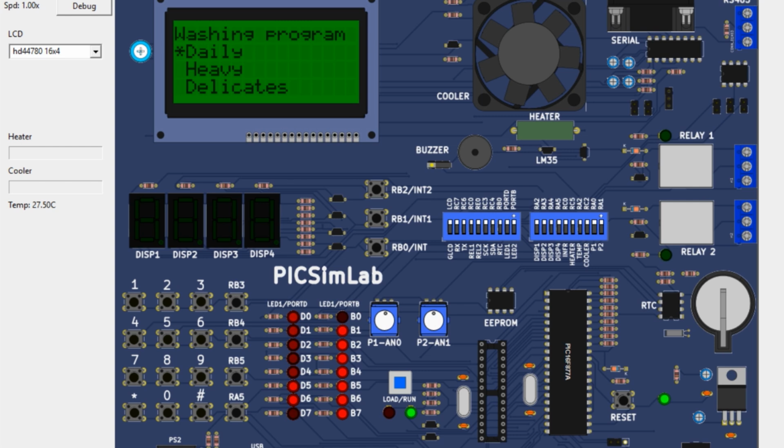And the PIC16F877A microcontroller is used because it is one of the most popular microcontrollers from Microchip because of its wide availability and low cost, and enough input output pins. As in the PPT, I showed the pin diagram of the PIC16F877A microcontroller. It has 40 pins, in that 33 input output pins. So we can connect LCD, buzzer, motor, keypad, etc.